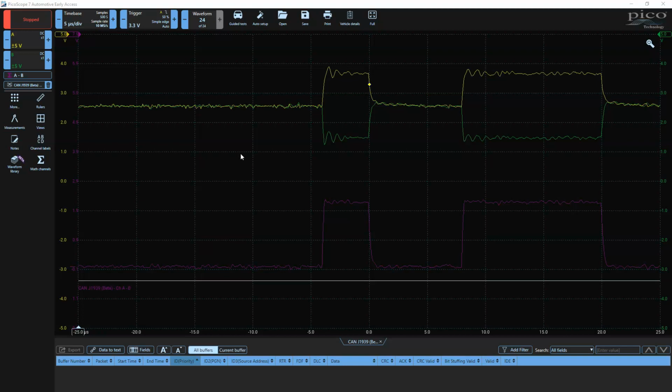I don't have a schematic for a device that I could show you. And there's not much that's out there on active termination. I'll just leave active termination up to the manufacturers to discuss. As I indicated, I think it's becoming something more of the past. I don't know. Let me know, put it in the notes. Besides perhaps the ISO bus, I don't know that any manufacturers use active termination on their CAN networks any longer. I think it's been phased out over the last few years.